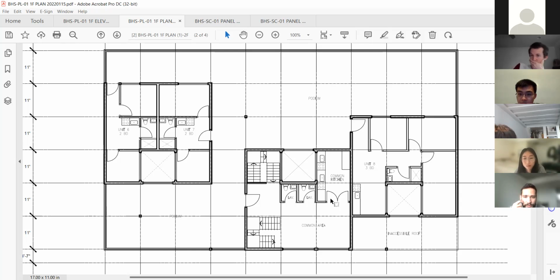For the walls, as you were mentioning, there will be structural walls, so at least the envelope, when I mean envelope, I mean the external walls, they will not be from drywall, right? So there will be some sort of structural masonry, probably concrete blocks. I think plywood. Usually, this is the second floor, we use plywood for lateral resisting. So it would be a wood frame. Wood framing, yeah. We won't go to steel or concrete.